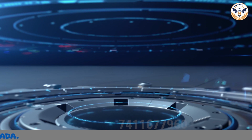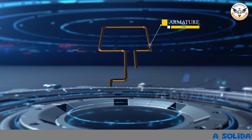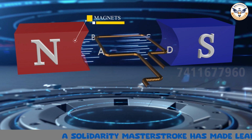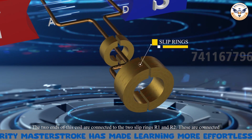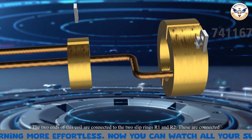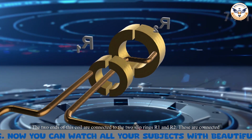Now, let's set up the simple electric generator. An electric generator consists of a rotating rectangular armature or coil ABCD placed between the two poles of a permanent magnet. The two ends of this coil are connected to the two slip rings R1 and R2. These are connected to the armature and thus rotate with it. The inner side of these rings are made insulated.